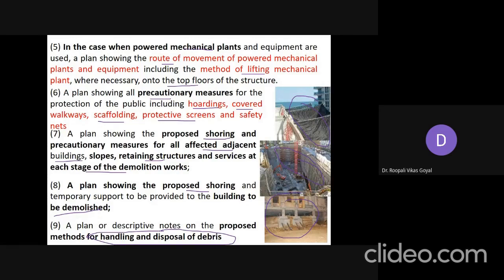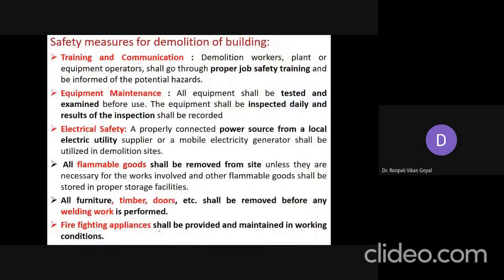Okay, so systematically you have to prepare the plan: sequence of demolition, safety of surroundings, and everything has to be mentioned in that demolition plan. So these are the safety measures for the demolition of a building. Okay, there are many safety measures to be taken before you start the actual demolition of the structure. So first is training and communication.